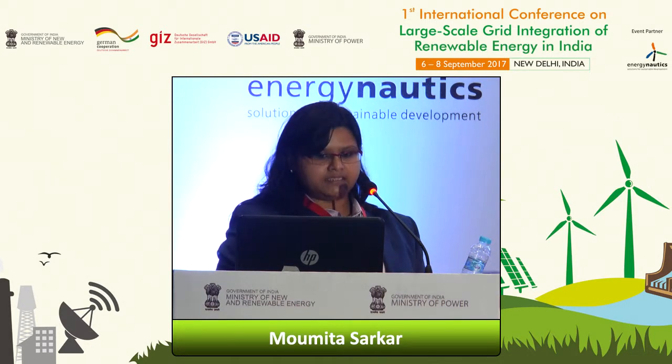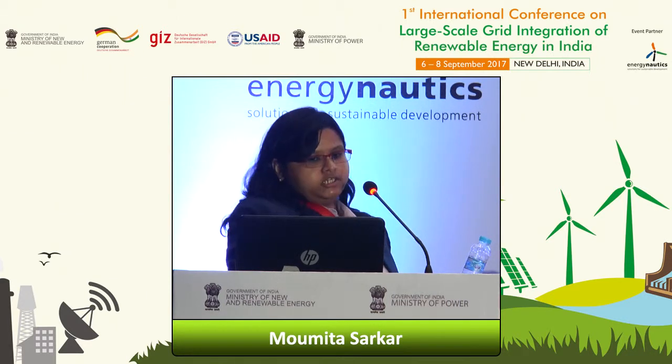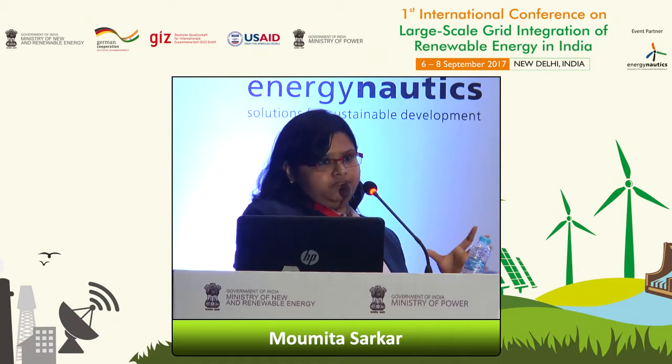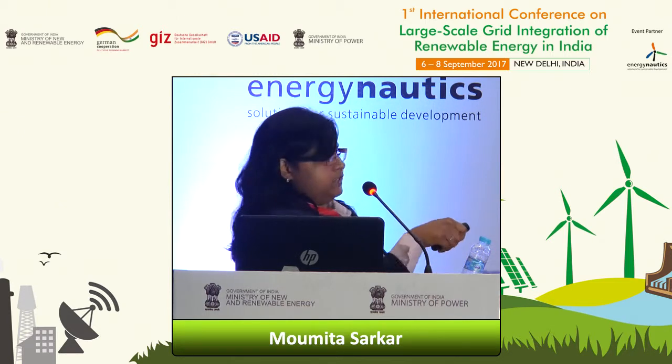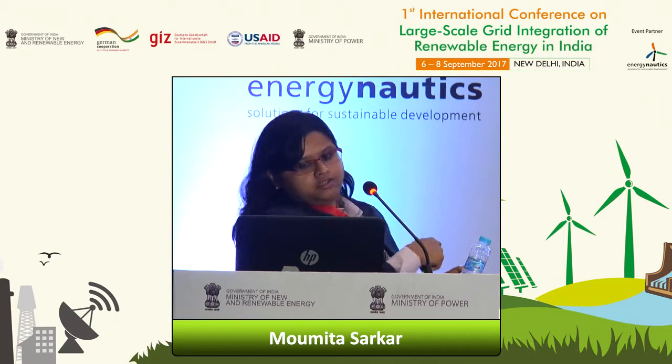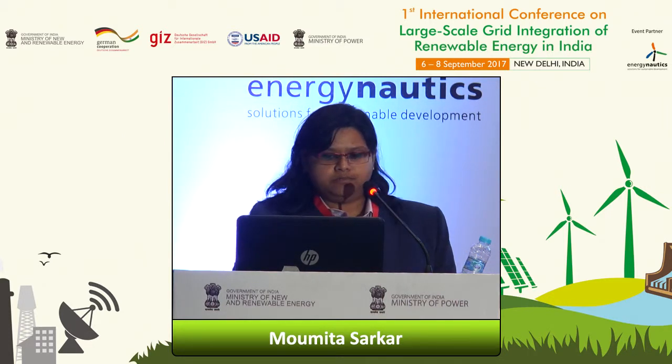So a centralized secondary voltage control has been proposed, where the capability of the wind power plant is taken into account. Here, in order to get 0.228 pu of reactive power support from the plant, we increased the reference voltage to 1.06 pu, which improved the voltage at bus 111 to some extent, to 0.94 pu.